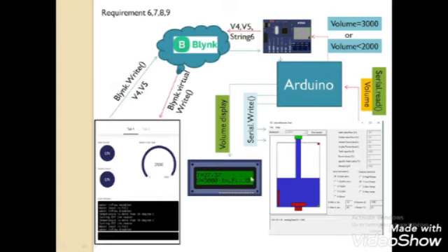If we go by the simulation, we will get a proper understanding of this slide, but still I will try to make you understand. So this is the serial tank. We can see these are connected via serial port COM1 and the Arduino is connected to COM2. So we are reading the volume via serial.read and giving it to the Arduino. If the volume is greater or less than 2000, we are sending it to the Ethernet shield.